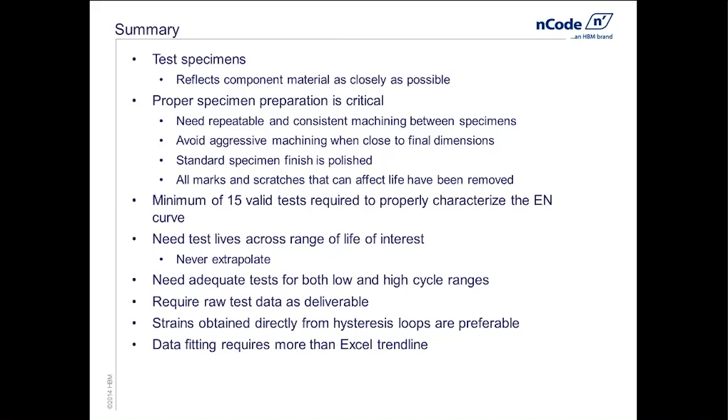And then finally, in terms of data fitting, the actual fitting of this data is more complex than just doing an Excel trend line. We're controlling the strains on the test, and the lives are the outcome. But basically the lives are the x-axis and the strains are the y-axis of our curve.